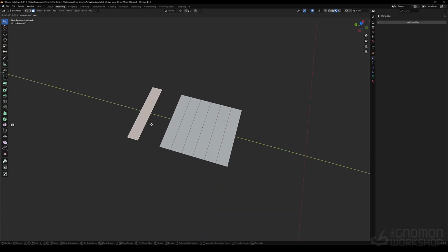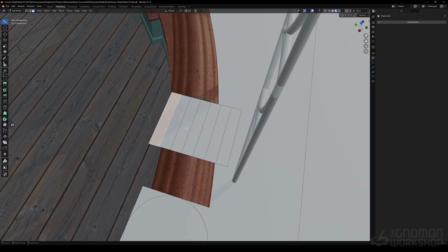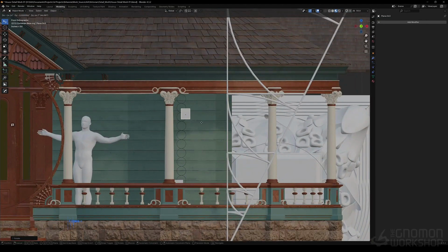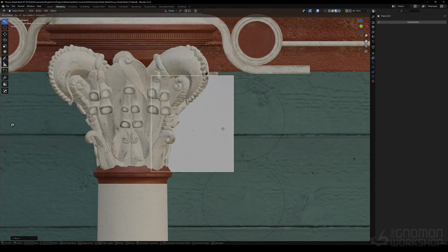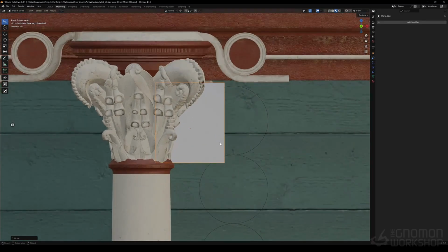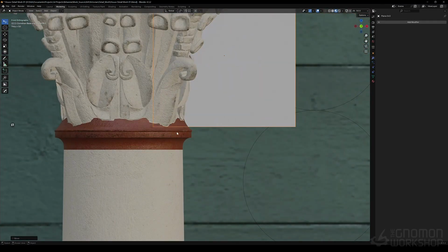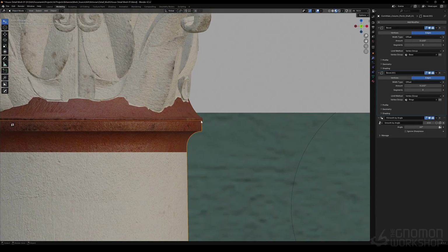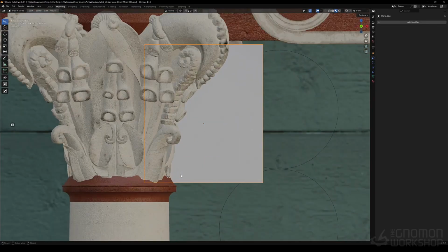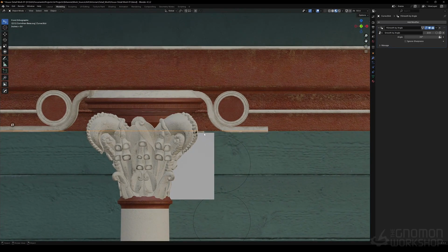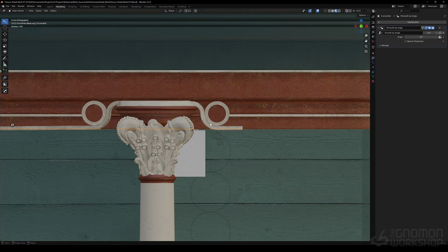And I'm going to take one of these pieces, duplicate it, put it at the top, and now I have 7/6 the diameter. And I will pull this to the top. And what I'm getting is a near perfect, well, I'm a little bit off because I scaled things a bit, but near perfect height of the bottom of my capital, right above this piece here, which is called the astragal. That should be 7/6 diameter below the architrave, which is this beam component above. And what is happening here is I am getting a proportioned capital piece.